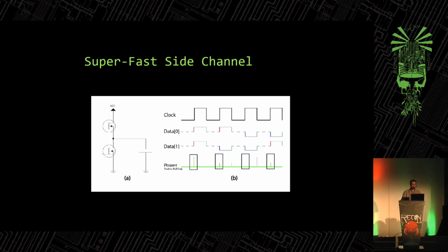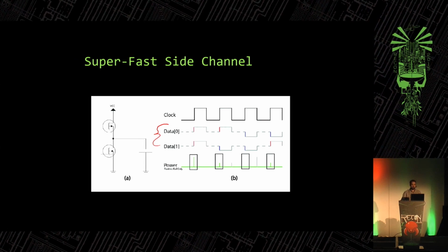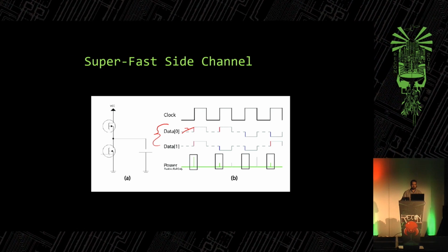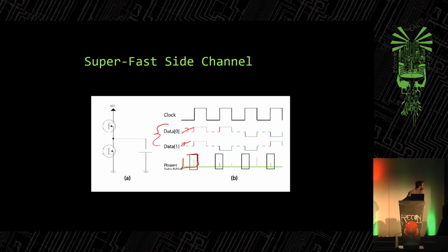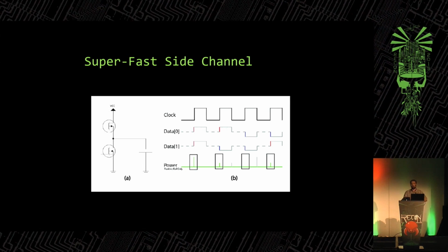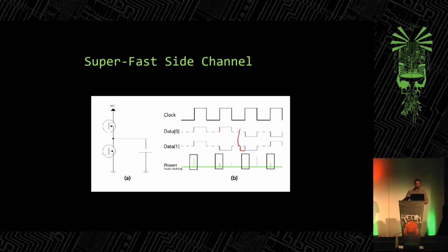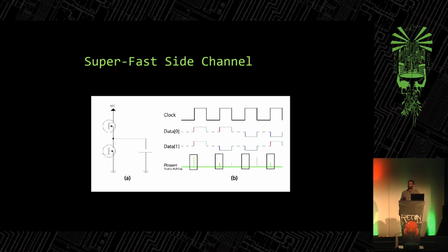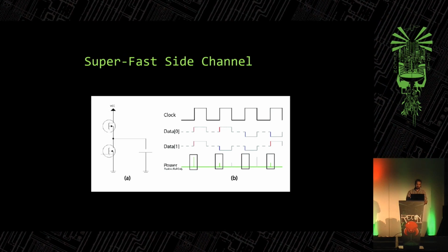And if we look on the chip, here I have two data lines. Those data lines always switch on the clock. If the two data lines switch from 0 to 1, I have two data lines here switching up, and you can see there's a spike of power if you can see it on the screen. Then later on, for example, the data lines switch low. I'm only looking at power consumed from one of the power rails. They switch low, so it doesn't take any power from the positive rail, so you don't see that spike. So the idea is that there's some linear relationship between power consumption and the number of bits set to 1 on the data bus.